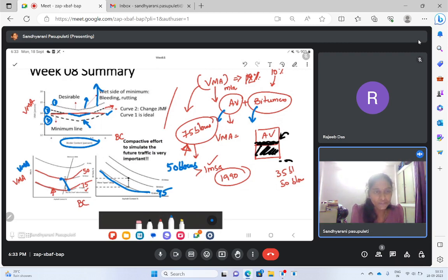Then all the air voids will remain as they are. Then air voids are more. What happens? There would be a circulation of more air in between the aggregate particles. Thereby oxidation of bitumen can happen and the mix will become brittle and there is a chance of water and moisture damage. So the selection of compactive effort plays an important role as much as VMA.